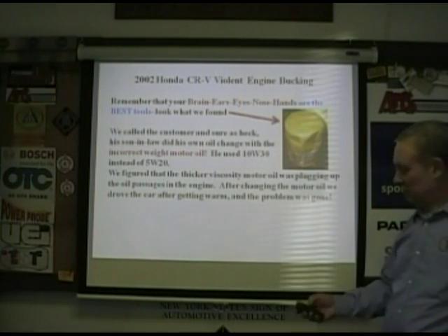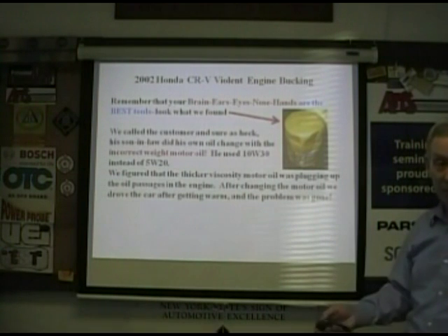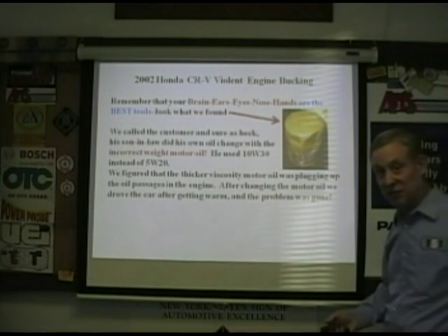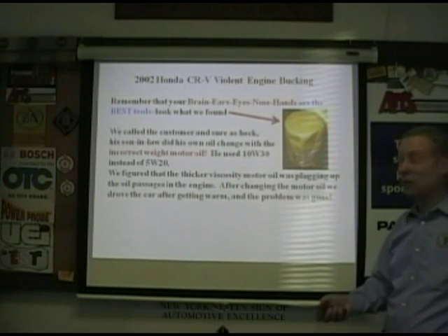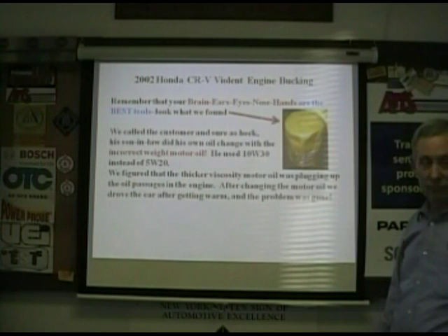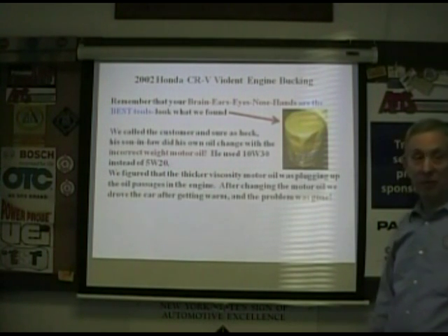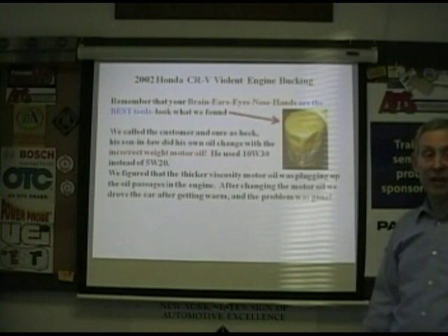Absolutely. And it can cause bigger problems because in a cold start situation, it might starve for oil. If it's 10 below zero, and we had some very cold days this winter, you might actually take the engine down. If it had happened in the summer, maybe it was hot enough that the oil thinned out and you wouldn't notice it.